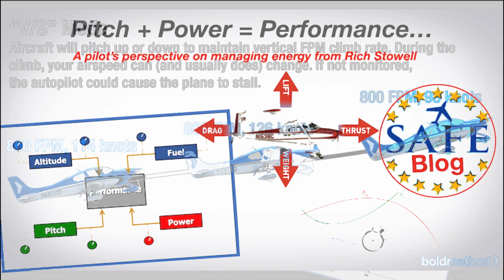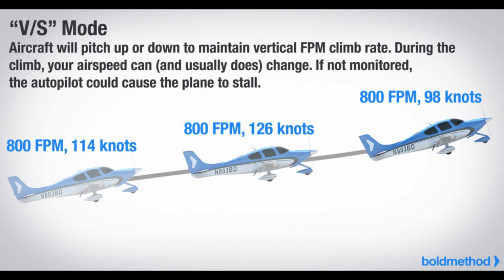Essential skills. 1. Use the FD/autopilot to climb or descend to and automatically capture and maintain an assigned altitude. 2. Determine the indications of the armed or capture mode, and what pilot actions will cancel those modes. 3. Determine if the system allows resetting of the armed or capture mode, or if manual control is the only option after cancellation of these modes.